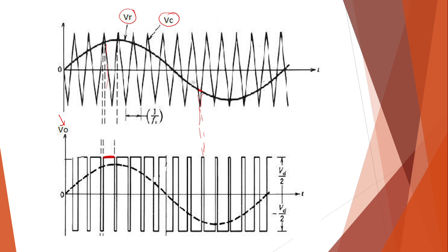Okay, so whenever your sinusoidal waveform is greater than the triangular waveform, at that time you'll be getting the output and you can just see how the width is varying. If you take the average of this particular value, you can see that it will be approximately a sinusoidal waveform. And in such waveforms, the harmonics will be the least. Not the order of the harmonics will be lower.